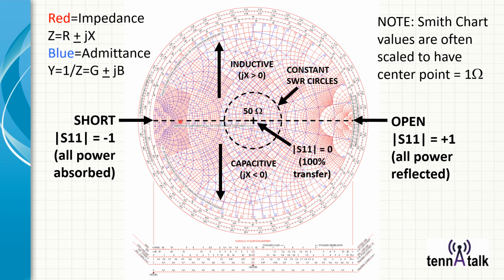If you see a Smith chart plot on your nano VNA, for example, that's along the horizontal, then you don't have any kind of reactance, okay? There is no positive reactance or negative reactance. Up here above the equator, you have a positive JX value, okay? That means the antenna is generally inductive. Below, it's capacitive, all right? And we'll get to these here in a second.